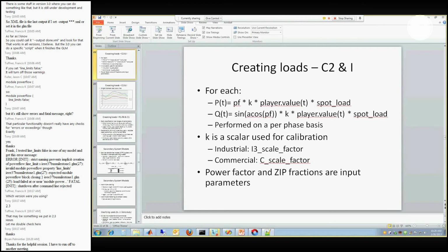So we've got low voltage ride-through by default right now. A little bit, yeah. Certainly the inverter models that we wrote in there are very generic. We didn't want to put a lot of those specific rules in there. But you could very easily go in there and write a rule inside the inverter model that would be, if voltage is under this level for 3 seconds, then we actually have an in-service and out-of-service flag, so you could knock it out of service and things like that. It would not take much to add that in there, so probably even as an external code extension through the runtime classes.